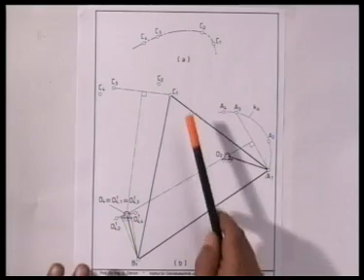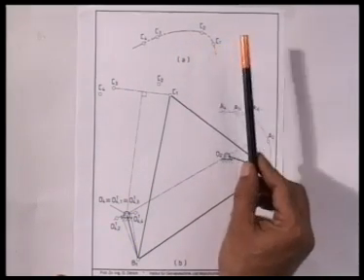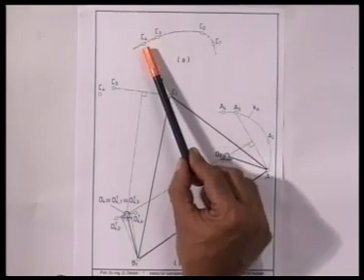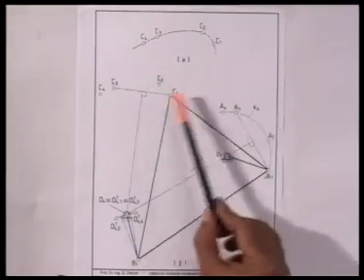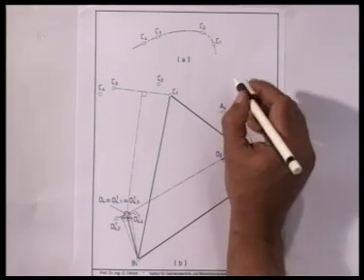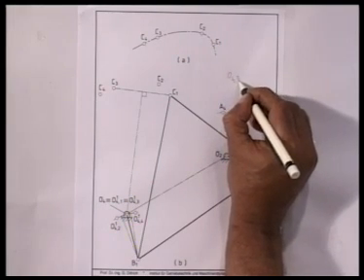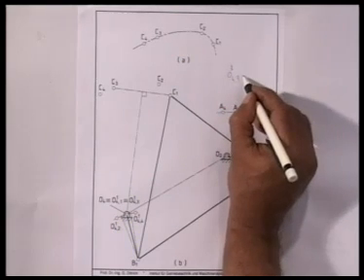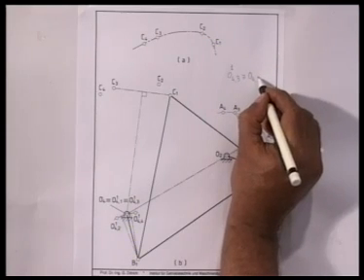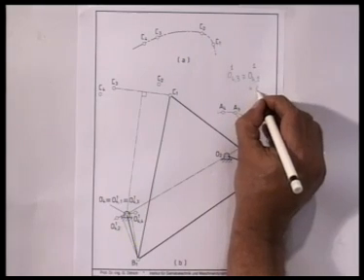Let me now explain this 4 position synthesis for the path generation. The coupler point of a 4R linkage has to pass through prescribed 4 positions, namely C1, C2, C3, C4. We shall apply the point position reduction technique such that 2 of the 4 inverted positions of O4 coincide, namely O4 third position inverted on the first position should be same as O4 first position inverted on the first position, which is nothing but the choice of O4.